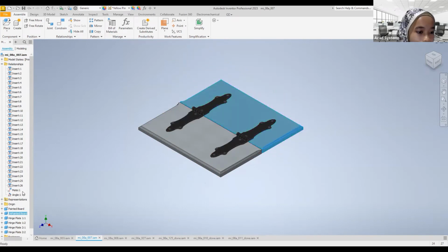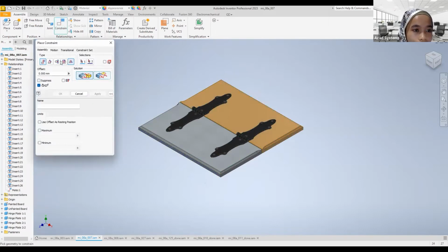Okay, and then let's try the last solution, which is the explicit reference vector. Okay, for the explicit reference vector, it will reach the default solution for the angle, and then the solution means we can select the z-axis. As you can see here, they have 3 selections, which is this. The 3rd selection is the reference vector that we need to choose. Okay, let's go ahead and apply.